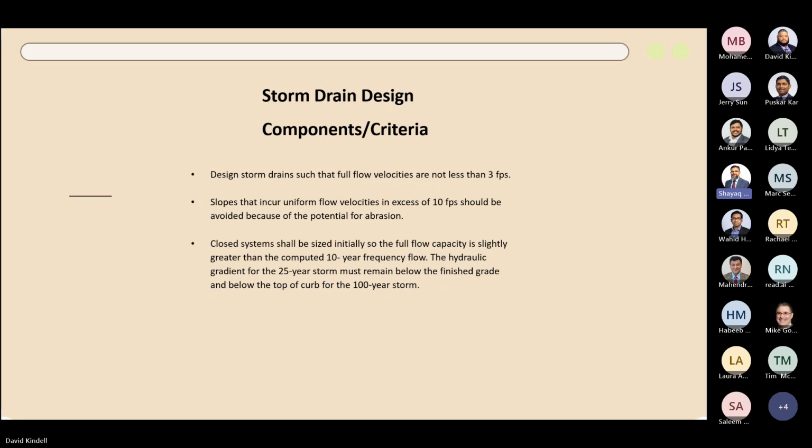Well, if you have the existing pipe inventory, you can give them the linear footage and the size of the pipes, because they need to know the size of the pipe. If the pipe size is like 18-inch, it's very difficult to do. But if the pipe size is a little bit bigger, then sometimes those 18-inch pipes are clogged. They cannot even pass through. So in those cases, they have to go to either side of the blockage, send the rover or the drone from the manhole from one side, and then go back from the other side and find out.